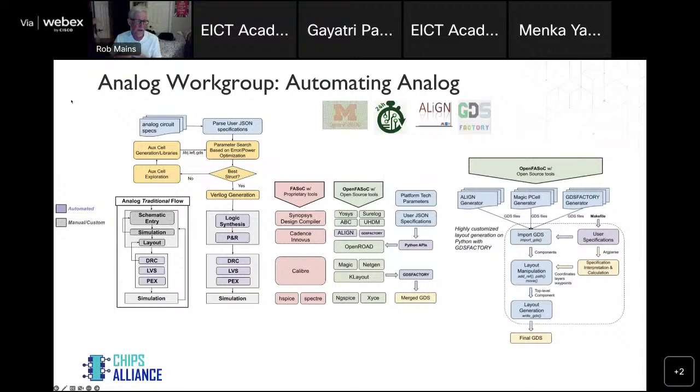You'll see on the far left the traditional analog type of flow, and that's very much, as I said earlier in the talk, how POWER4, as an example, was designed, using pretty much all schematic entry and going through those steps. Sun Microsystems tried to do the same type of thing. But what we've seen, because of the problems relative to productivity in both analog and digital design, is that a more structured, cell-based approach for both analog and digital makes a huge difference in productivity, time to market, and fewer designers required. So that's a huge improvement.